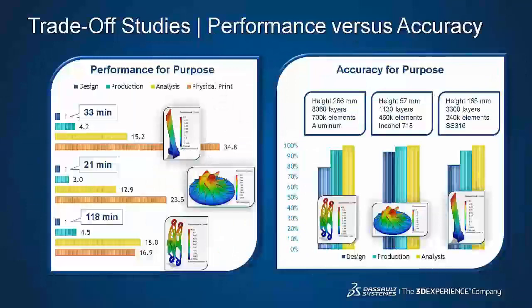Real value in process simulations for additive manufacturing comes from the ability to arrive at a successful build configuration without physical trial and error. But for this to be possible through simulation, the run times must be significantly faster than build times without a significant loss in the accuracy of the results. Because our simulation framework allows for the solution fidelity to be controlled simply through the mesh sizes and time incrementation, we are able to study and quantify this trade-off in solution accuracy versus performance.